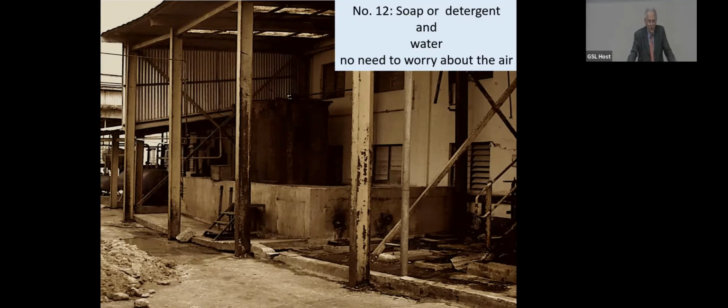Water and add a bit of detergent. This was in Nigeria. The detergent seemed to have a completely dispersing effect on the local clays, so that the ground was just collapsing wherever there'd been a leak of detergent. And it was the very dilute detergent that seemed to do it, and particularly the detergent precursors. And the collapse front was just propagating down, so that buildings with deeper foundations were affected later. They were mainly strip foundations, but the deeper they were, the longer the time.